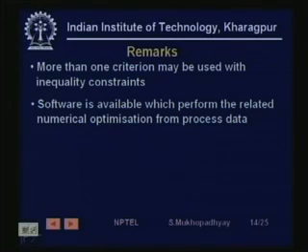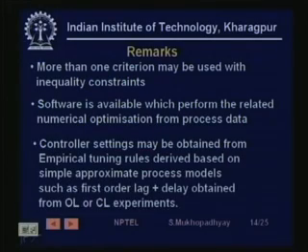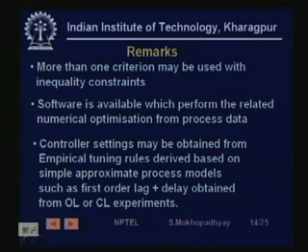Now all these that we have so far talked about generally assume that model forms are available, but in many cases you may not exactly be able to obtain the form of a model. Then you must model the process using some simple model structure based on some experiments. So you actually perform an experiment, see the response, measure certain properties of that response, and then design your controller based on that. Typically you can have either open loop experiments or closed loop experiments.